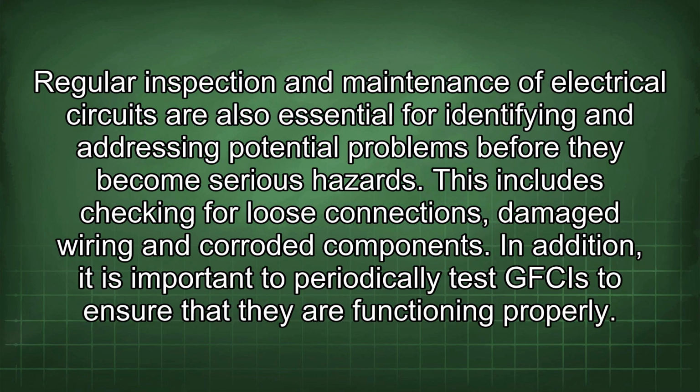Regular inspection and maintenance of electrical circuits are also essential for identifying and addressing potential problems before they become serious hazards. This includes checking for loose connections, damaged wiring, and corroded components. In addition, it is important to periodically test GFCIs to ensure that they are functioning properly.